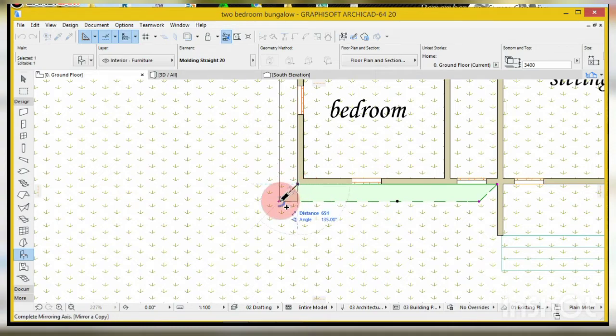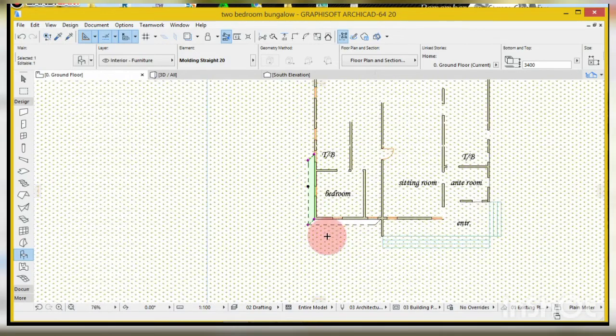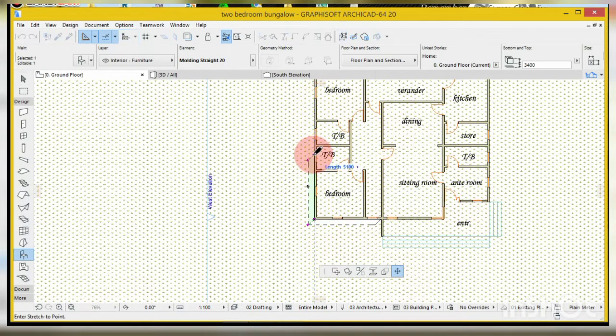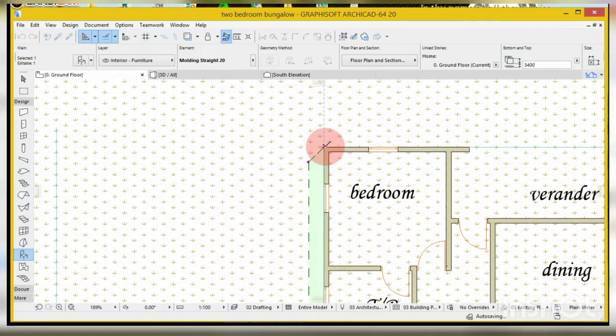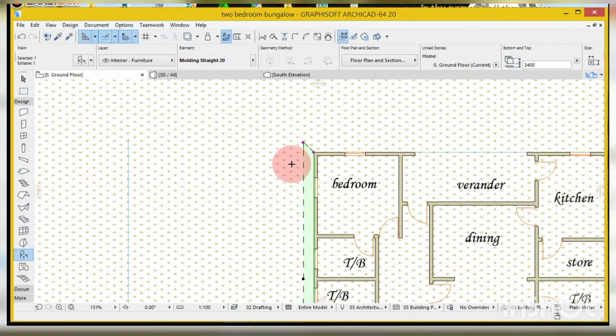You come to this point. As you click here, you come to this point, you drop it. You now stretch. That's how to put the parapet to stretch to this point. Then you click at this point, you turn it this way, angle 135 degrees and 45 degrees. That's what will make it up. Control Shift M to drag the one going to the other side.